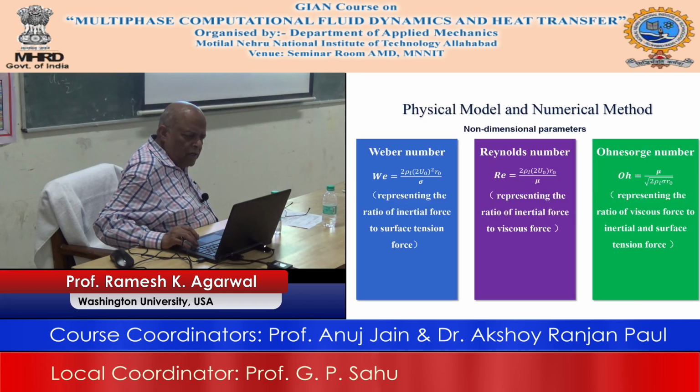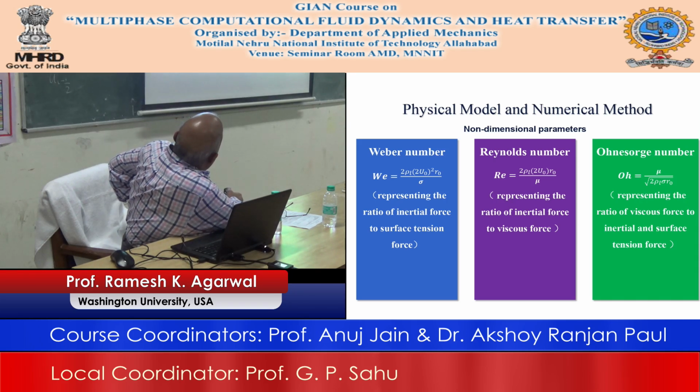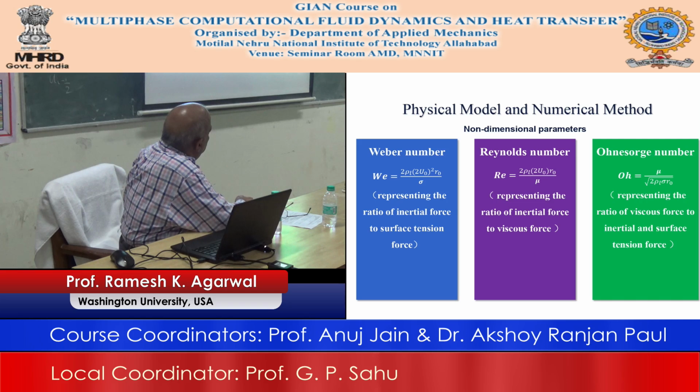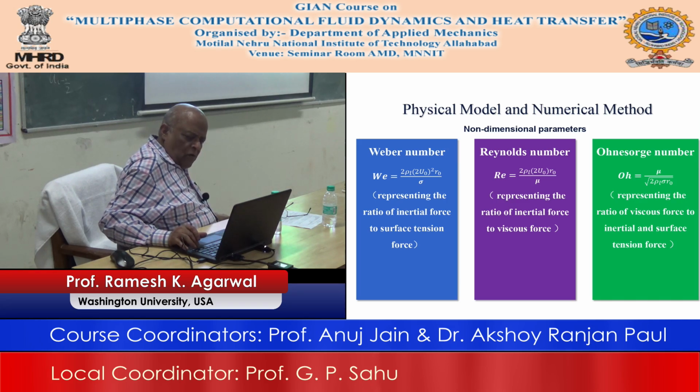Now again, as I said, what are the important parameters? The Weber number is always an important parameter in this case, and the other one is the Reynolds number, and then the other one is listed as the Ohnesorge number. If you look at what we discussed in the second lecture, this and this can somehow be combined together, and there may also be some other combinations. This was given to you in the second lecture. So you can use these non-dimensional parameters to study the properties of this collision.